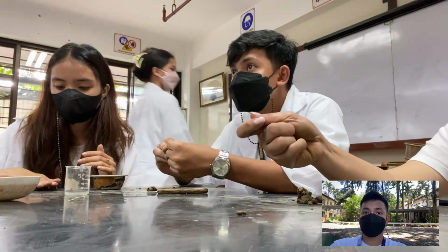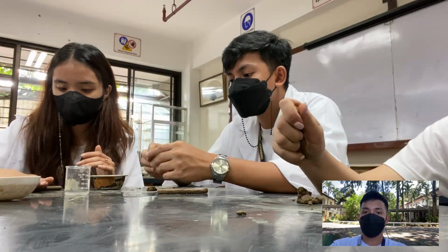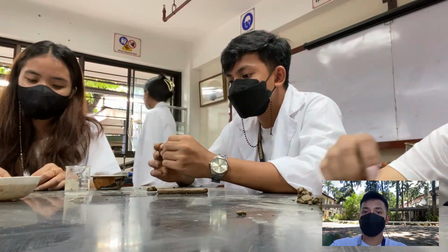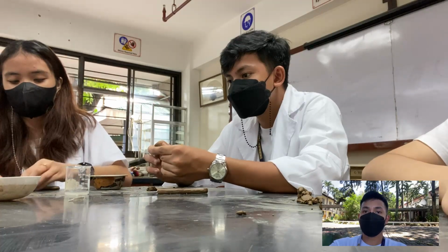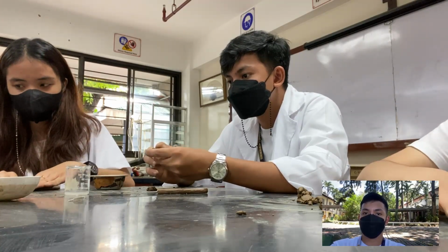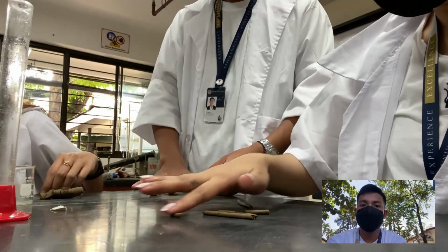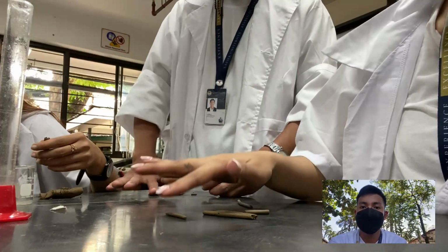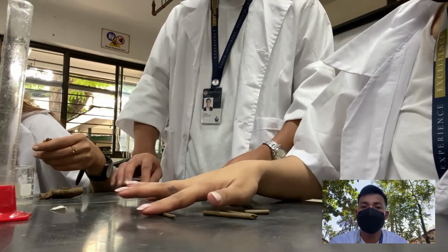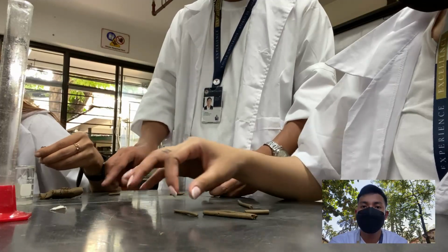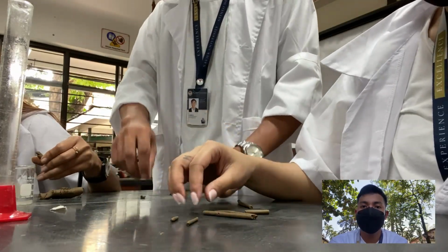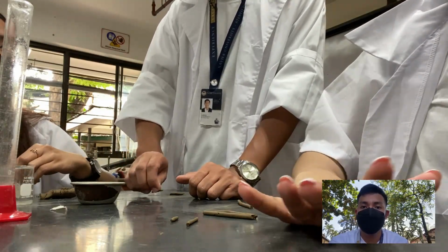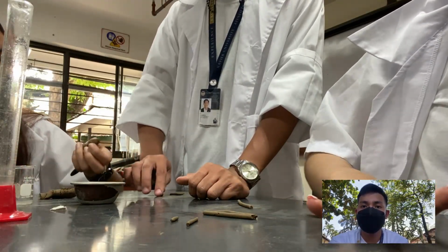Take note that a stroke is one complete motion of the hand forward and back to the starting position. The thread shall be deformed so that its diameter reaches 3.2 millimeters or 1/8 inches, taking no more than 2 minutes. When the diameter of the thread reaches the correct diameter, break the thread into several pieces. Knead and reform the pieces into ellipsoidal masses and re-roll them. Continue this alternate rolling, gathering, kneading, and re-rolling until the thread crumbles under the pressure required for rolling and can no longer be rolled into 3.2 millimeter diameter thread.